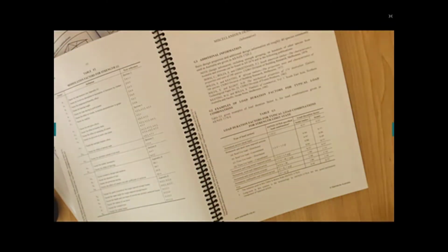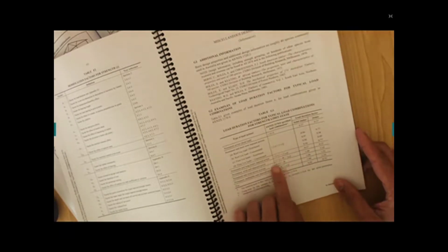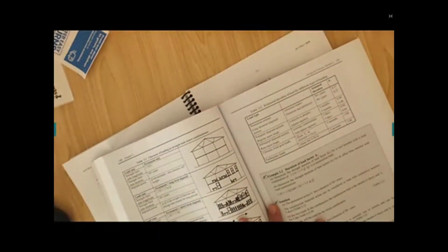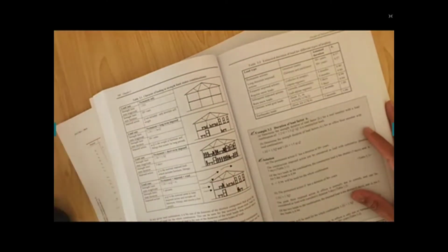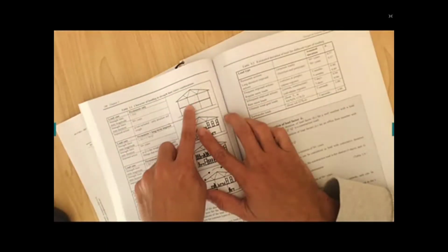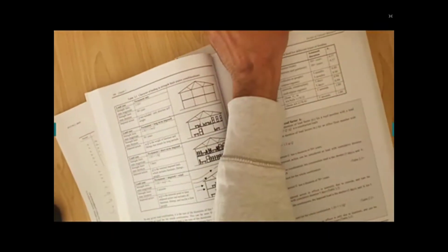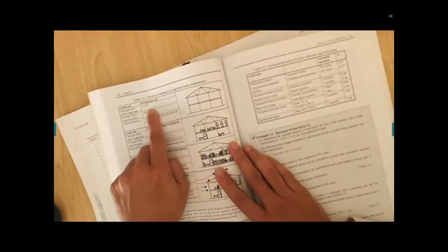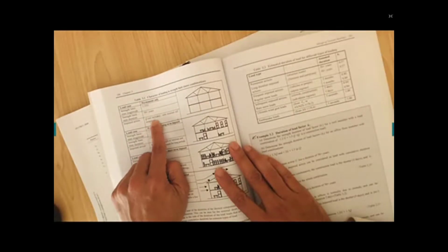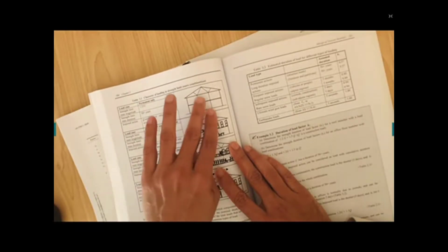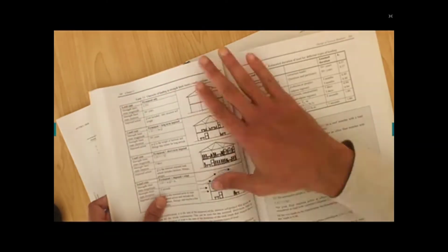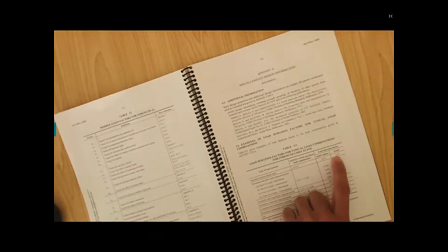Now, I hope you have these dead loads, live loads, wind loads, and short-term factors, and you have different cases. These figures are going to help me. You have 1.35 G, or you don't have any occupancy. You have just the structure. So 1.35 G, 50 years, and Q not included, only the structure self weight. So in that case, just the self weight of the structure. 1.35 G, quite serious. That is 1.35 G, 0.85, 0.57 for this one, quite a high penalty.